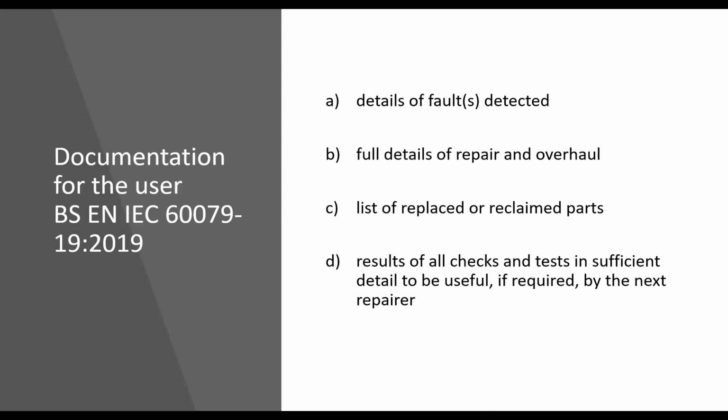Now, this is the documentation that should be sent to the user according to the international standard. Details of all the faults detected. Full details of the repair and overhaul. List of reclaimed or replaced parts. And the results of all checks and tests in sufficient detail to be useful if required by the next repairer.